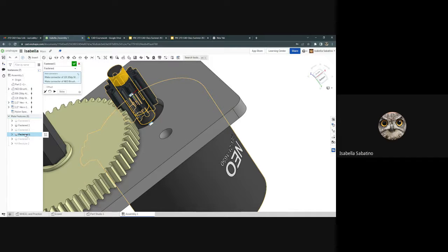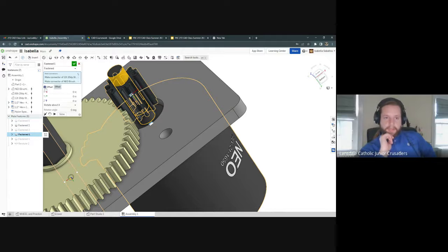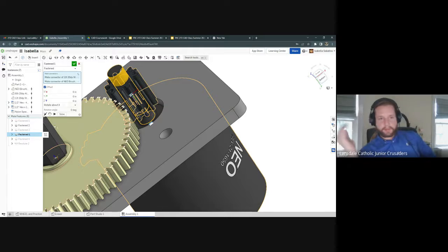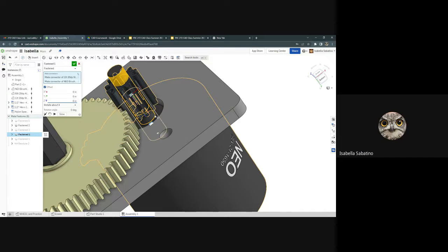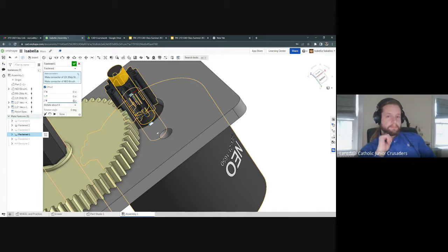Do I check it? Yep. You click the checkbox, and that'll apply an offset, but everything's 0 right now. And I'll give you a hint. The Z-axis is the axis about the shaft, like that goes through the shaft. So what do you want to do? Yep. I gotta bring it down from here to the motor plate. Not all the way to the plate. Just like a portion of the way. So put in a number and see if it works. Like type in 0.25 or something. That looks like it's a little bit too far.